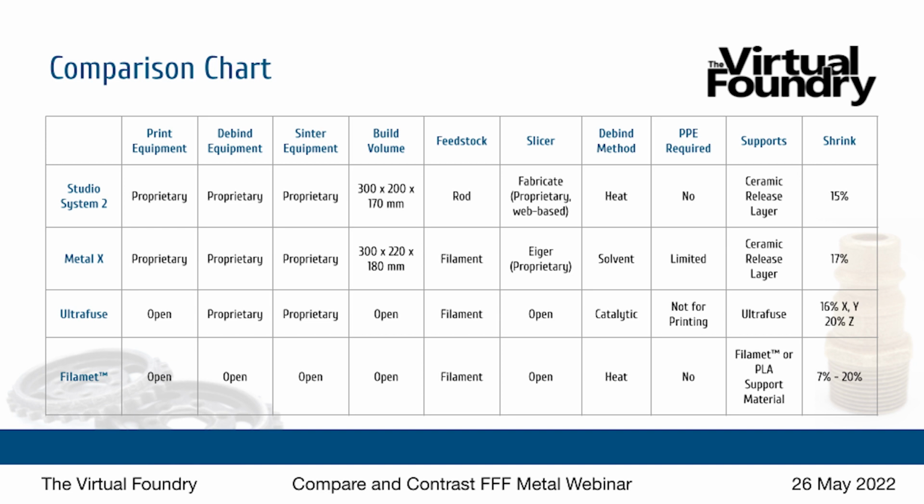Right. And you're working with powdered metals in each of these situations. And sort of one of the key advantages over the bound metal strategy of metal 3D printing is that there's no air in contact with the powders. So the powders don't become airborne or anything like that. At each phase of the process, they're bound in some way. Yes, and the only exception to that would be if you were to file your part, then you are definitely releasing metal powder. But if you're working the process, print, debind, sinter, no metal powder is released into the air.